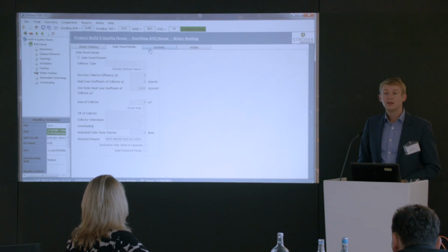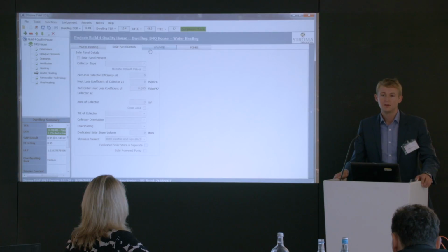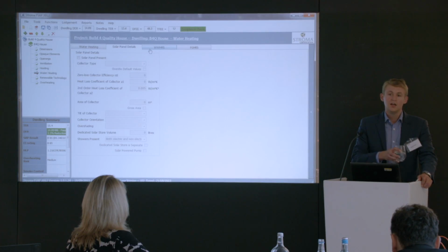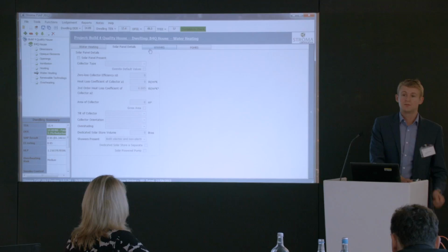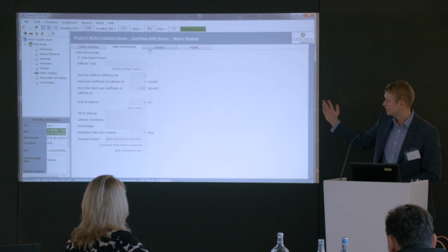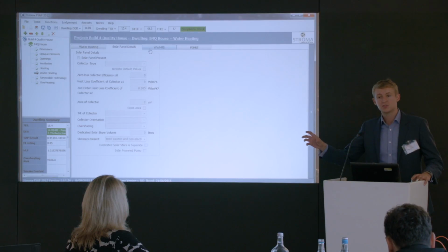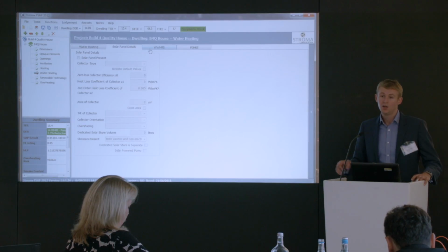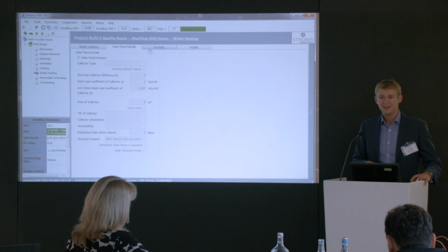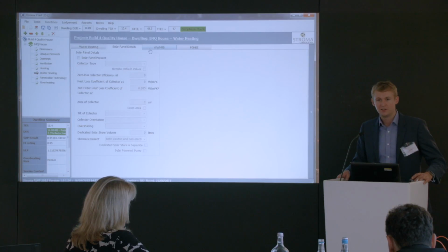And then, let's take into account occupancy. SAP makes assumptions on occupancy. So if I have this home here, which is, I've forgotten how many square metres, a couple of hundred square metres, SAP assumes it will be occupied by a certain number of people. We don't have any control over that. If this was a one-bed home that was 200 square metres and a big open plan, the water heating demand would be exactly the same in SAP as if this was a 5-bed home. So you do find that it's just a flat assumption. We don't have any control over that.